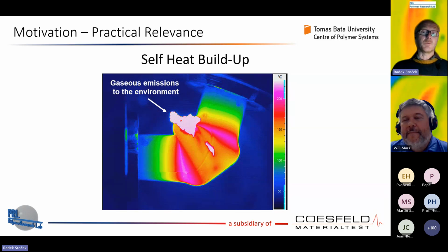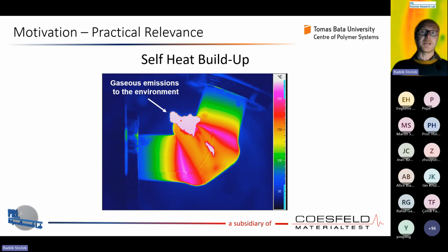When we speak now about truck tires, for example, these are mainly based on natural rubber and partly on synthetic rubber like butadiene rubber. That was exactly the example which Will showed in this video. It was natural rubber, and natural rubber will really be inflated by the gases due to temperature, which can be more than 200 degrees Celsius, coming up to 300 degrees Celsius. This is an amazing temperature for sure. And after really blowing out, the material is totally destroyed, and the gases are coming out.